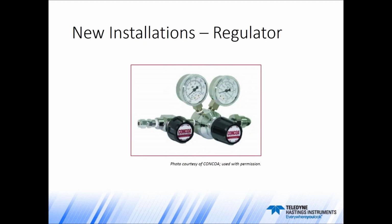Also mention that proper selection of a regulator is important. An undersized regulator can lead to oscillations in the flow controller because the instrument may be starved for gas.